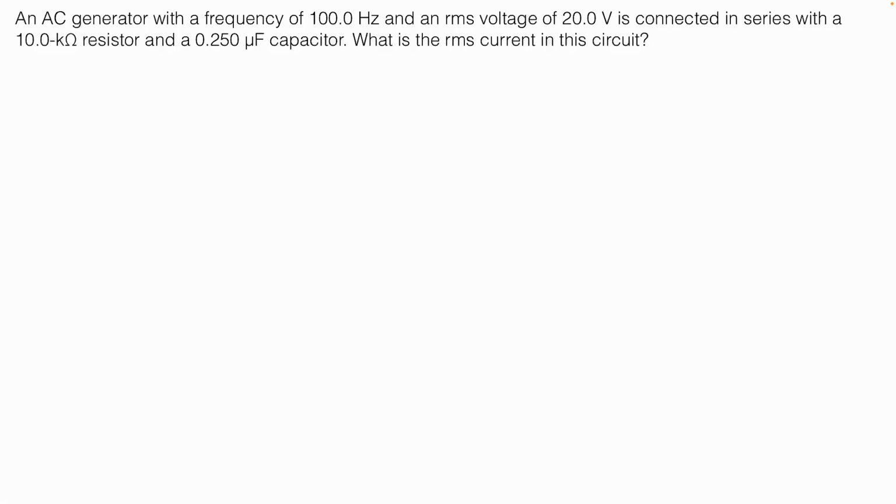It's a series RLC, but we can take out resistors, capacitors, inductors, and all of our toolbox still works, right? If something's missing, if you have a circuit that maybe is only RC or RL or just LC, just set the effective resistance of that element to 0. So in this problem, what have we got?